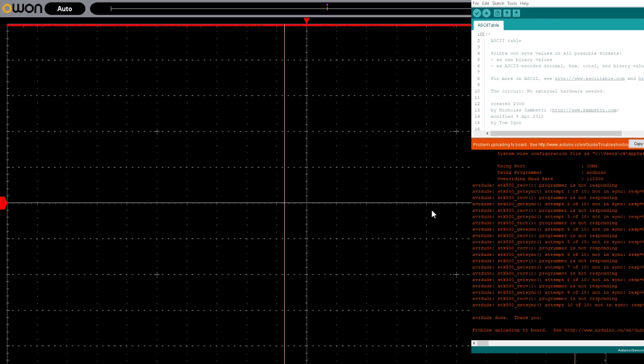Then the RX and TX: pin 2 on the FTDI to pin 3 on the chip, and pin 3 on the FTDI to pin 2 on the chip. And then I've got 0.1 uF capacitors between the power for the chip just to do some evening, and that capacitor between the reset wire and the wire to the first pin.